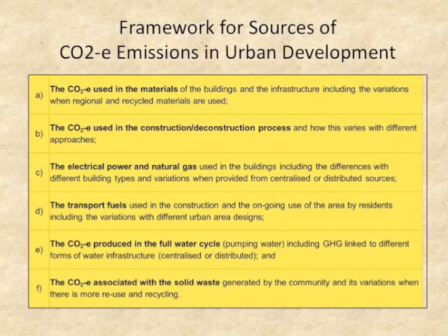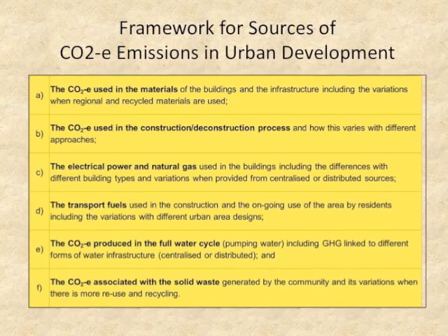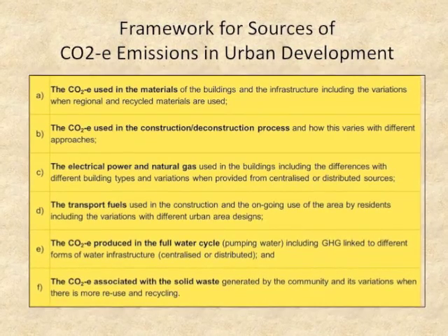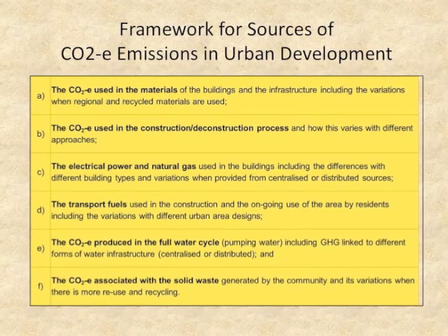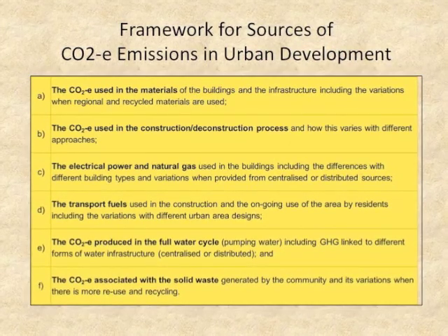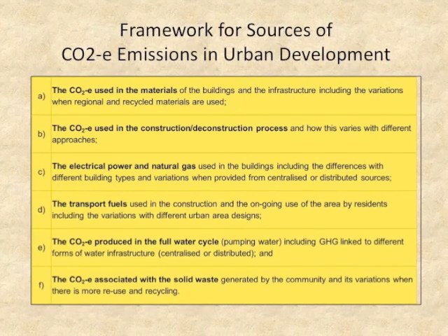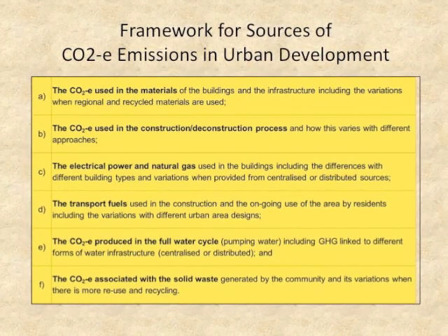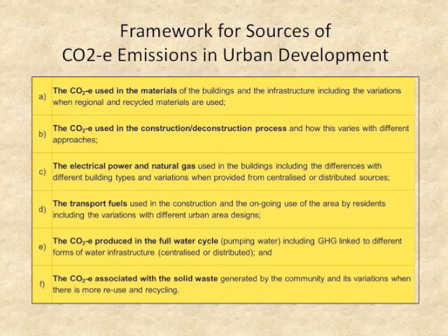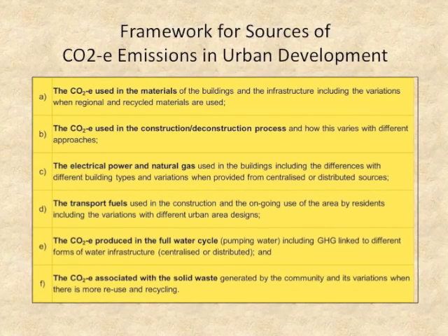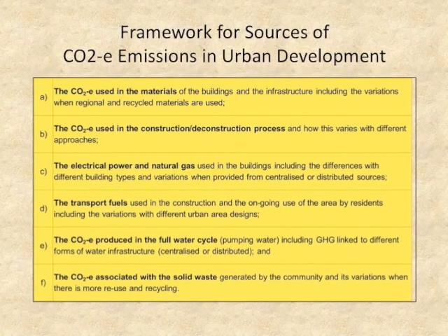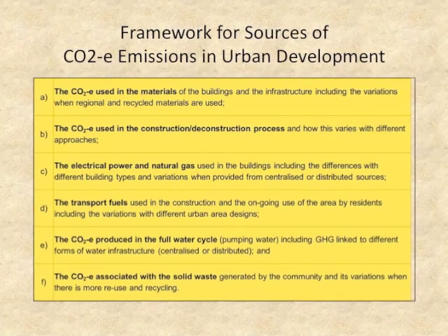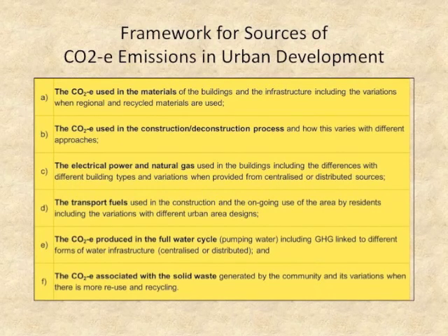A carbon assessment tool is required which considers the carbon metrics for all the sources of emissions in the life cycle of an urban development. These are outlined in our study's framework, including the carbon emissions used in the materials of the building and infrastructure, carbon emissions used in the construction-deconstruction process, the electrical power and natural gas, the transport fuels, and the carbon emissions produced in the full water cycle, as well as the solid waste.